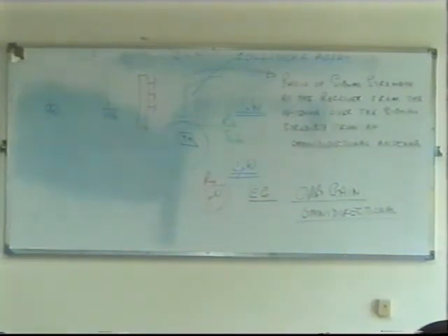It depends on the frequencies. See, at the airport, when we talk about HF communications, you'll notice that your receiving antennas are a few kilometers away from your transmitting antennas, aren't they? This is HF communication now. The reason being that your transmitting antennas are very powerful, and if they were very close to your receiving antennas, they would overload the receivers, I should say. Probably just to improve the signal-to-noise ratio at the receiving end, yes. I mentioned, I think last week, that they use 10 kilowatts maximum power for the transmitter. This is for HF. Now remember, HF is nothing to do with line of sight. We're talking about using the ionosphere there, so it is a different system altogether.